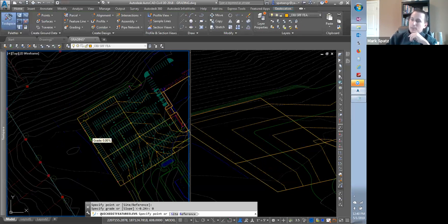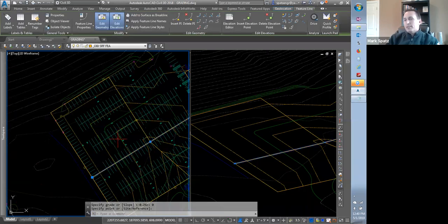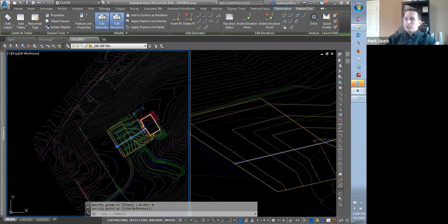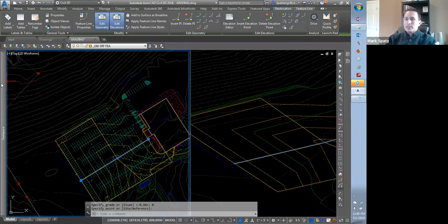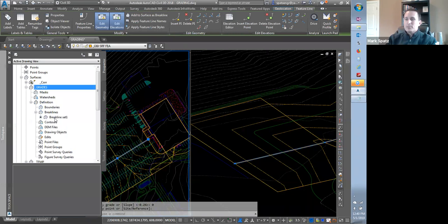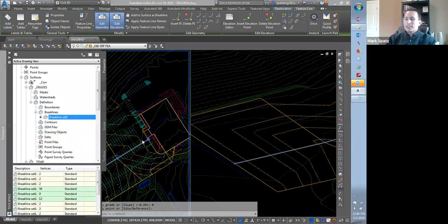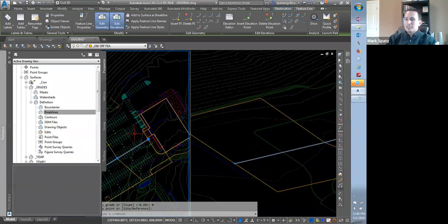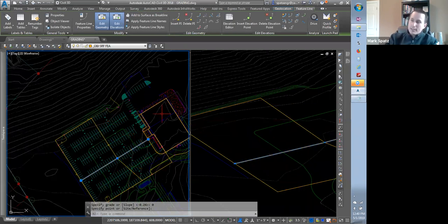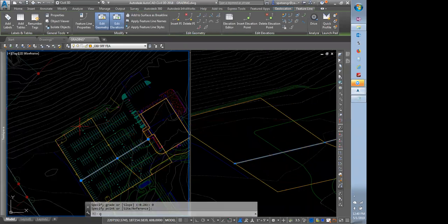Now back to where I was. So these break lines are dynamic to that surface if you want to make auto rebuilds. Now, as you add more break lines, like we have a lot more to draw in up here, you wouldn't just add those as more break line sets. You would come in, right click, and delete the entire break line set from the surface. It wipes out. Then you add the break lines again. You would do Q select.